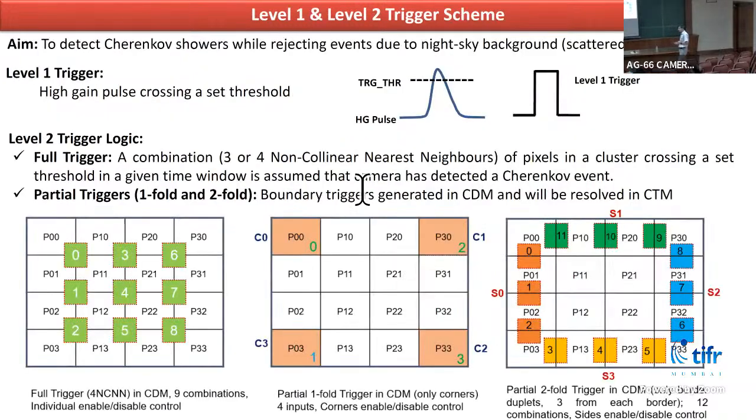Yes. I'm also going to describe a little about how you arrive at the particular threshold, because the SiPM may also have some amount of background noise, and how you discriminate and how it will affect the threshold and your final data. Right now we can configure the threshold. In the results section, I'll show how this trigger threshold is decided. I'll cover that at that time.